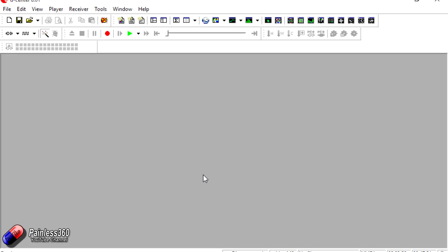So here we are in uCenter. I've downloaded it and started it. We have the GPS connected as per the diagram. So now we're going to see what we can actually see. Hopefully we'll see why the CC3D Revolution hasn't been happy with the GPS. So I'm going to click connect. At the bottom we can see it has connected. It's saying it's COM7 9600 baud, but it's showing as an NMEA protocol. We don't want that, we want it to be all u-blox stuff. So now we know that that's the problem, we'll go through and configure this GPS to be u-blox, so we can plug it into the Revolution to use.